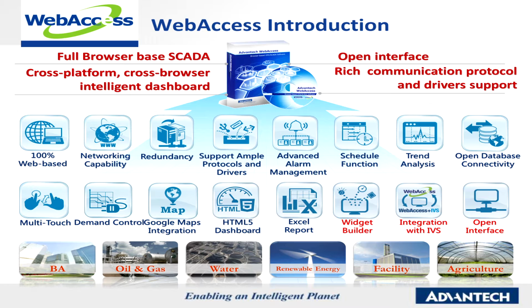WebAccess provides compelling SCADA functions, including advanced alarm management, scheduling, real-time trend charts and historical trend lines, support for ODBC communication, and rich form and report functions, such as user-defined reports in Excel format.